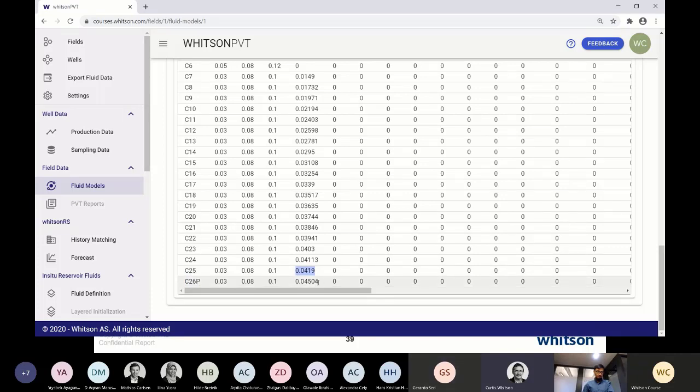But if you need to fit a bubble point or dew point of this system, and you change the BIP of C1 to C26 plus, and it goes to 0.23, what they can argue, and they're probably right, is that it's dangerous to start doing predictions of MMP, of compositional gradient, where that heaviest C26 plus component is really important: its phase behavior, its fugacity.